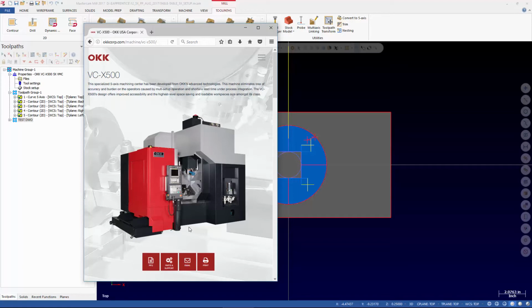It doesn't make sense to try to do a 5-axis multi-axis cut on a part that's prismatic. Said clamps right. Is that not for M38, M39? Well, it's really going to depend on the machine tool builder. Not spindle gear. I'm talking C-axis and A-axis clamp and unclamp. Usually it's like M10, M11 for one of them, and then like M19, M20 or whatever.